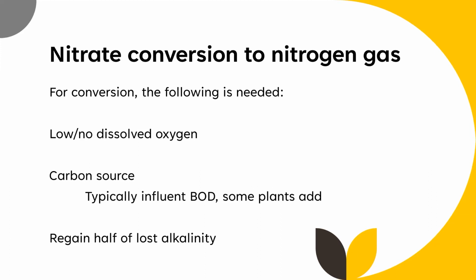To have denitrification, you need low or very low or no dissolved oxygen to occur. And I'm getting something that my connection is unstable. I'm going to turn off my video here. You also need a carbon source, which is typically going to be that influent BOD. So again, some plants need to add from time to time. When you convert that nitrate to nitrogen gas, half of the lost alkalinity is recovered, which can be very beneficial to operational sustainability at a facility.